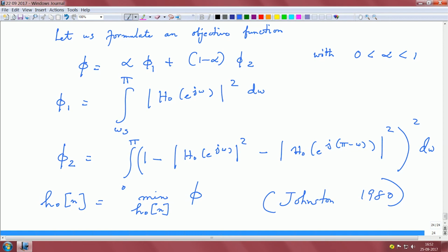Okay. So this completes our work on analysis of the 2 channel filter bank for alias cancellation, for phase, for minimizing the phase distortion, and then for minimizing the amplitude distortion. So you have to keep in mind, first you start with the alias distortion, you figure out how your synthesis filters have to be chosen to eliminate aliasing distortion.